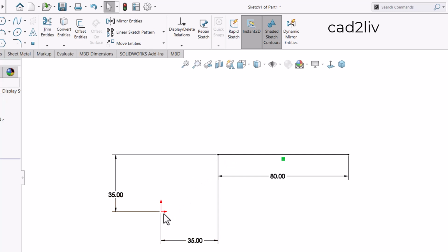So we are sure that the origin is going to control this line, otherwise there is no sense in giving the dimension. We are giving the dimension with respect to a reference, or with respect to 0 0. Otherwise there is no meaning left to give the dimension. I hope you got the answer why we need the origin, so that we can control the dimension.